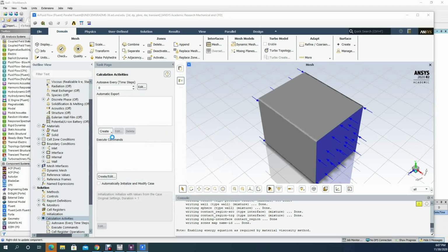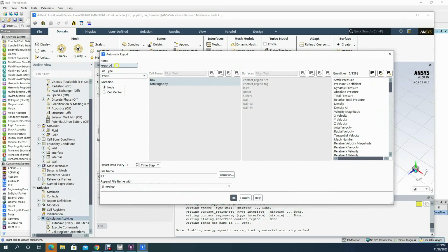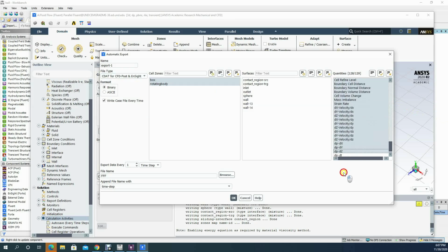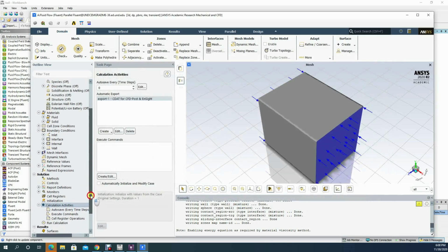solution data. So under solution data, change this, then you could select all this, and time step. So you could say for every time step, I plan using 100 time steps. So let's say for every 10 time step. Yeah, you could change this, you could make it lower to capture more of what is going on. So let's say 5. So 5 time steps.